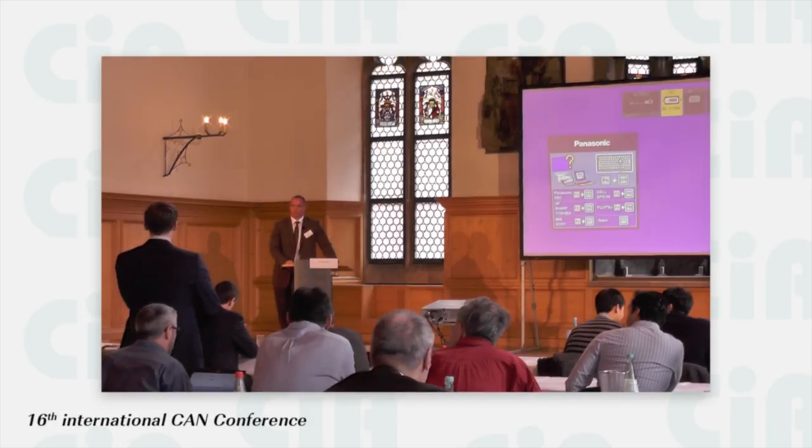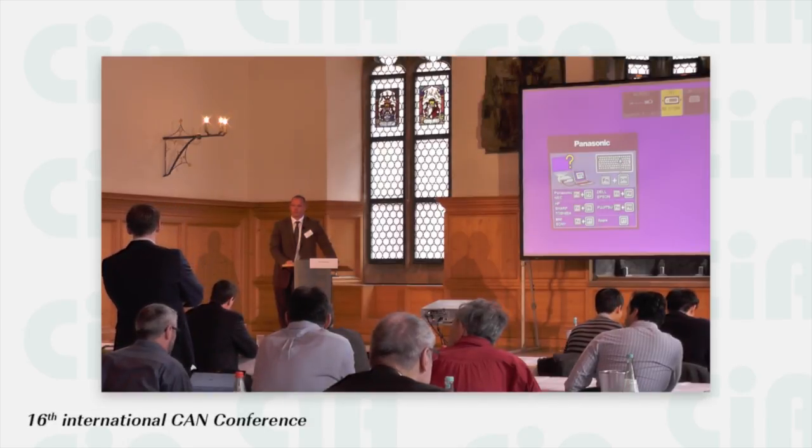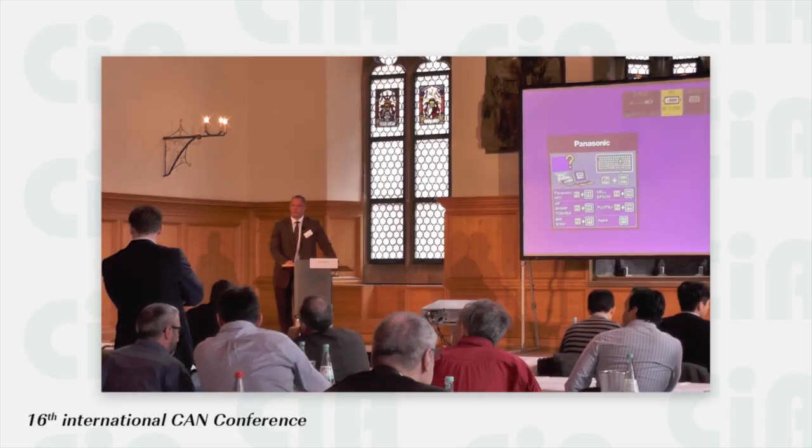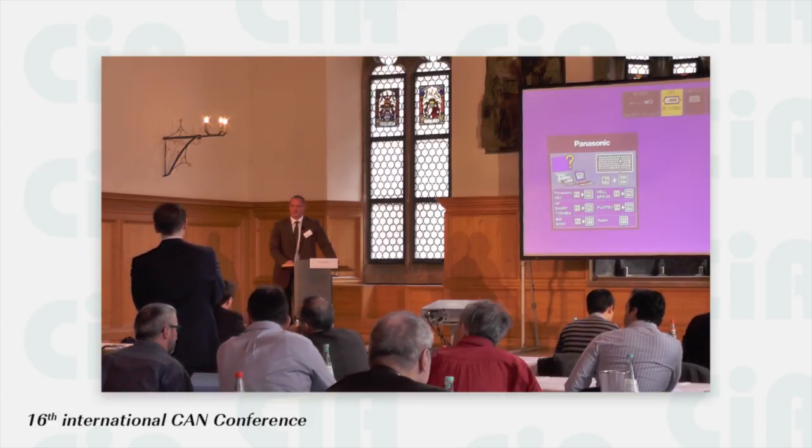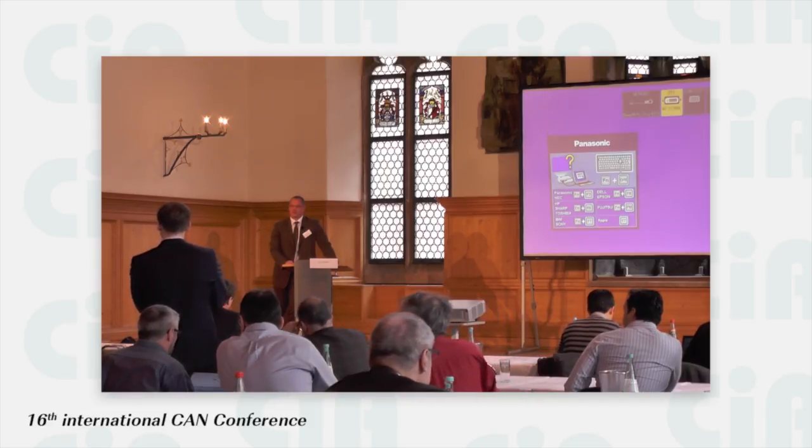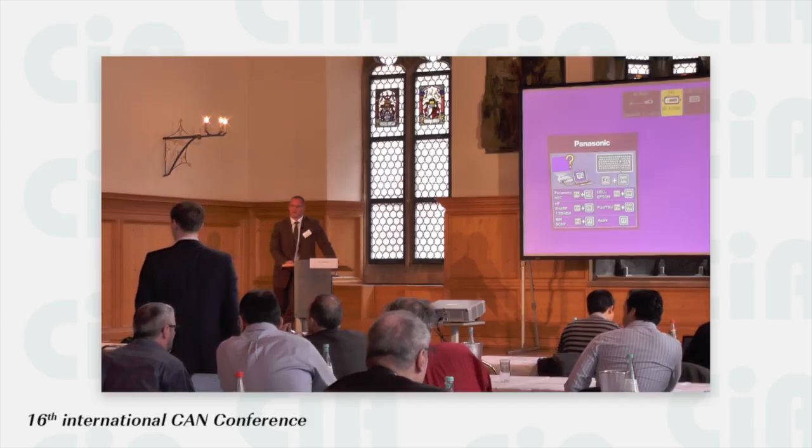One moment, please. I already had a chance to test this tool. It was not fully implemented, so some features were missing, like the mask and so on. This was at the last Plugfest in Nuremberg. And it's a great tool, so this is the first thing. And the second, when you showed these eye diagrams, you measure on the bus. This means the impact of the receiving transceiver is not measured. At the moment, not. Now you could cover this by defining a mask that is more strict to cover the impact of the receiving transceiver. Or what is your idea how to cover the impact of the receiving transceiver?